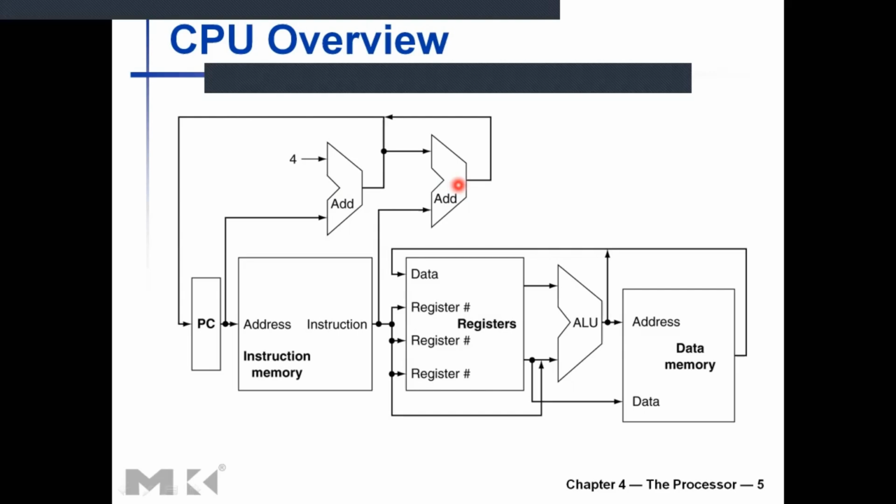Okay. So next we have the register file, right? So based on the type of instruction, once the instruction is fetched into the CPU, we decode it. Some logic circuitry inside the CPU needs to decode this instruction, and once you decode it, you have different fields. You have register numbers, you have immediate operands, you have shift amounts and function fields and all that.